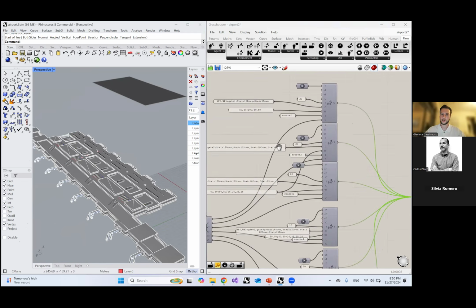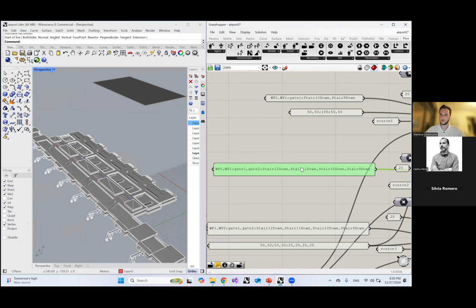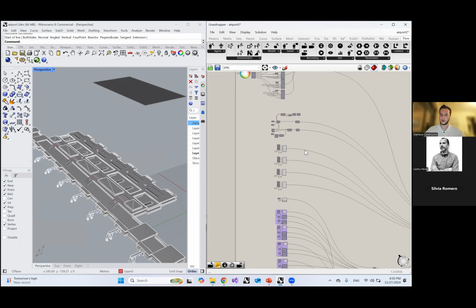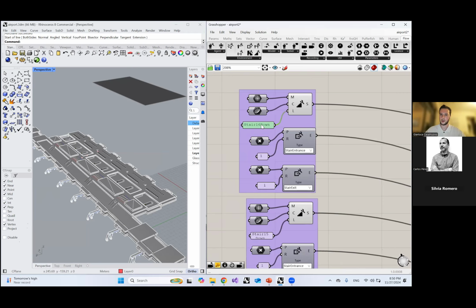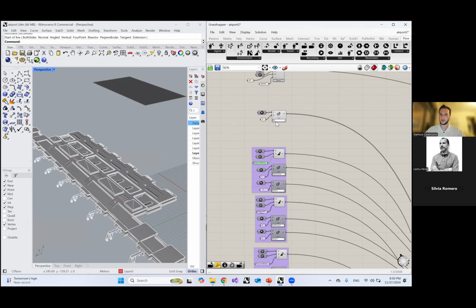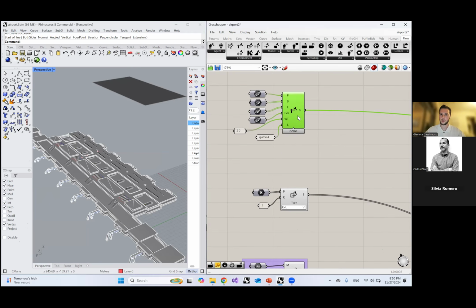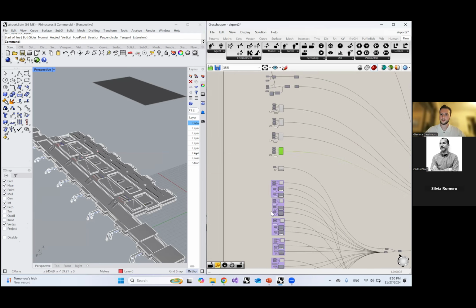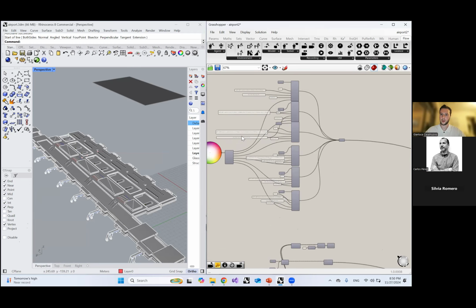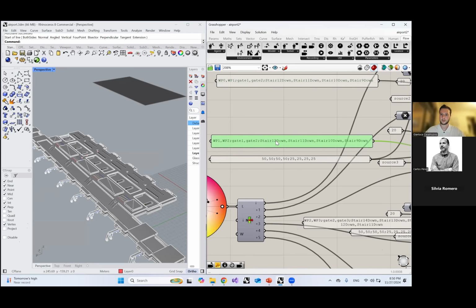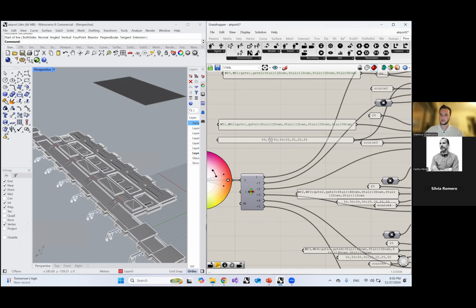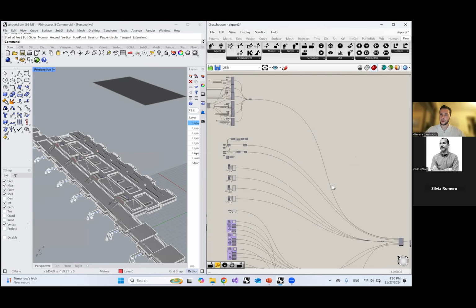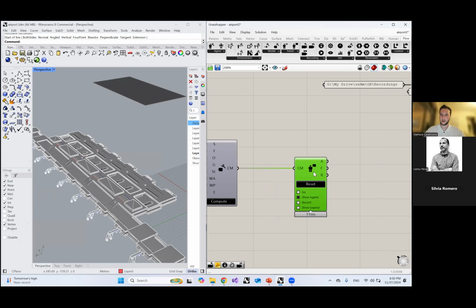And each source has combinations, which are basically the labels that I insert in the basic parameters, which I create in Grasshopper. So based on this label, I can create combinations. As I explained before, comma if it's the same level, semicolon if it's a different level, and weights, okay? And once the model is set up, I can simulate it.